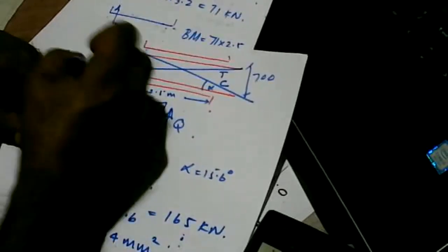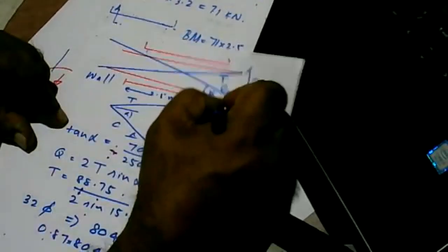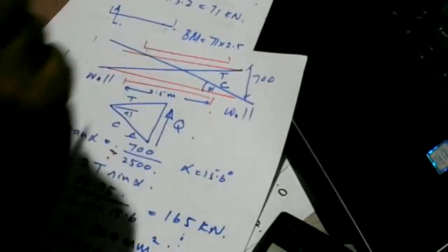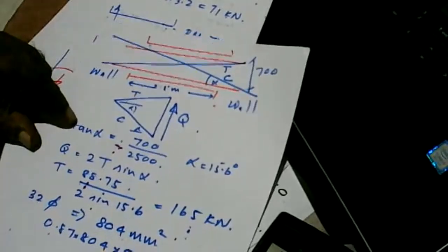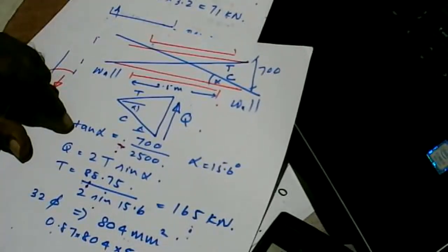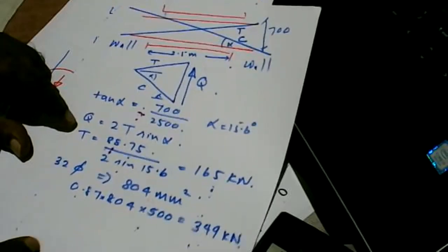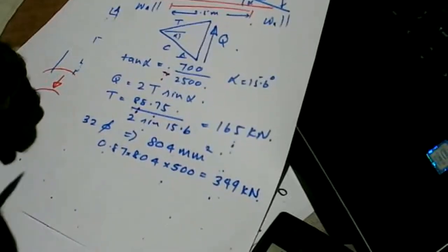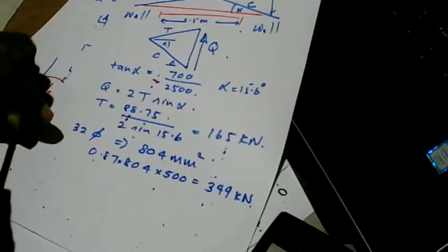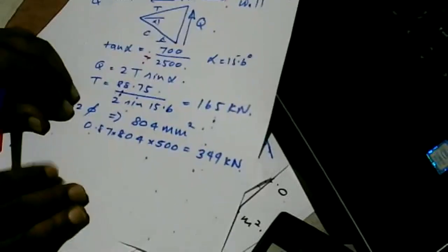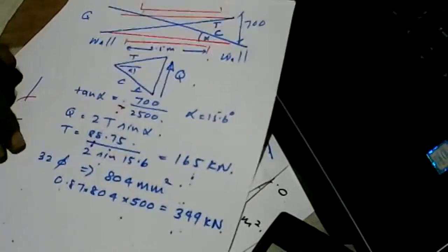Beam wall junction is, this is the wall, and here at this junction you can get these additional plastic hinges forming in ultimate situations. And to prevent that happening, we generally provide this diagonal reinforcement as well. So that is some additional information for you.